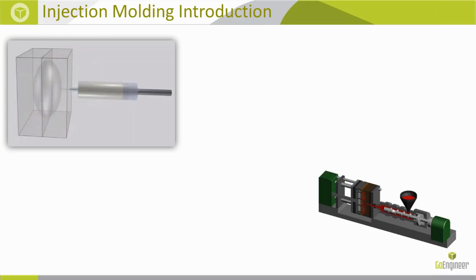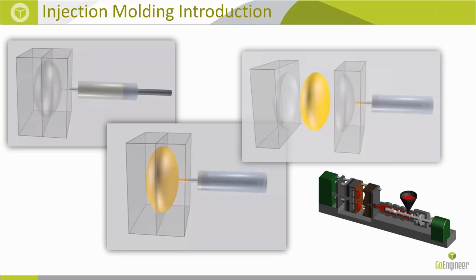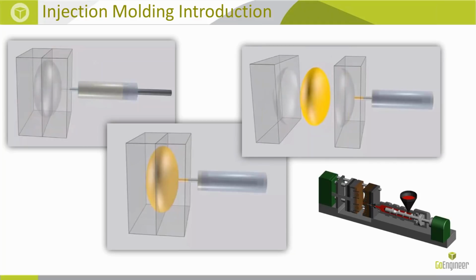The pellets become molten plastic, which is then injected into the mold. Once your part is injected into it, the part then cools down after occupying all the space inside and solidifies, and it is then ejected out to drop outside. This is the injection molding process.